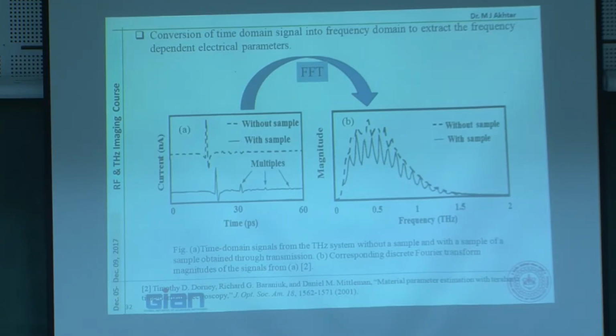The other approach is that if you are a physicist, usually you have a femtosecond pulse laser. So you have a time domain pulse, you excite the sample using this time domain pulse, and you want to get the response, whether in reflection or transmission mode. And in this case, because you are working in time domain, if you want to use the data in the frequency domain, you use FFT. Both have their pros and cons. And again, as the Professor was saying, whom do you ask? If you ask engineers, they say the multiplier is very good, the femtosecond pulse laser is not good. If you talk to physicists, they say multipliers have a lot of noise, and the pulse laser is good. Anyway, both are used depending upon what you have, but both are expensive. They are not that easy to achieve. So that's the main challenge.